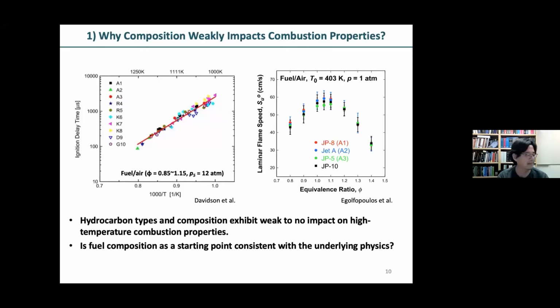That work is ongoing, and whether the system of equations can be closed mathematically, in other words, whether we need more information than a cetane and octane number to get to NTC chemistry, I cannot answer at this moment. My colleague Hai Wang's point of view is that the octane number and cetane number are simplistic. Those are engine-based properties that may or may not give you full information about NTC behavior.